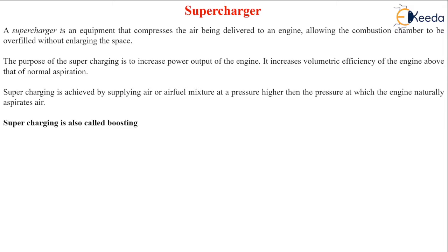We have already studied in case of SI and CI engines the conditions required for proper ignition and proper combustion of fuel. As far as SI engine is concerned, if the temperature and pressure at the start of combustion is on the higher side, then this might lead to pre-ignition, or in other case, this might lead to the charge being ignited before the flame reaches and consumes it. This will ultimately result in detonation and knocking.